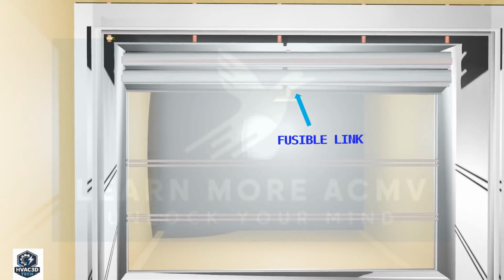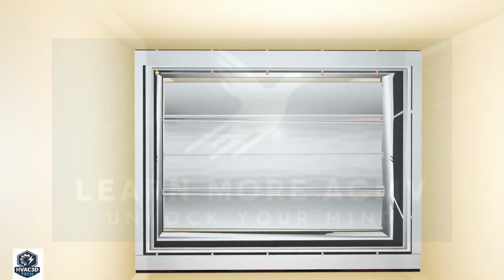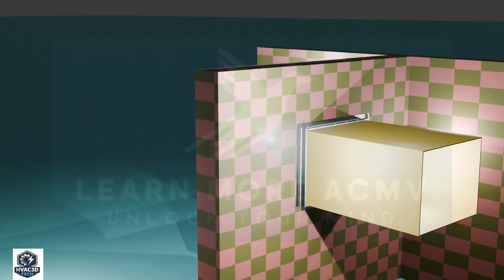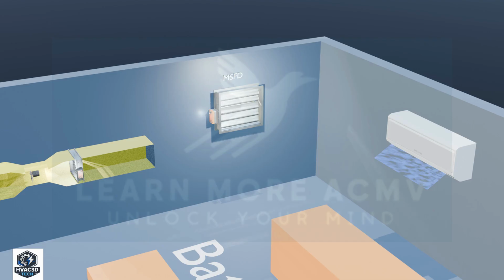Under normal conditions, the fire damper remains open. When a fire occurs, the fusible link melts, causing the damper blade to drop and close the duct opening. In certain areas, such as battery rooms, fire codes do not permit the use of conventional fire dampers. The intent is to prevent fire and smoke from other zones from entering the battery room. Therefore, an MSFD is provided at the battery room instead of a conventional fire damper.